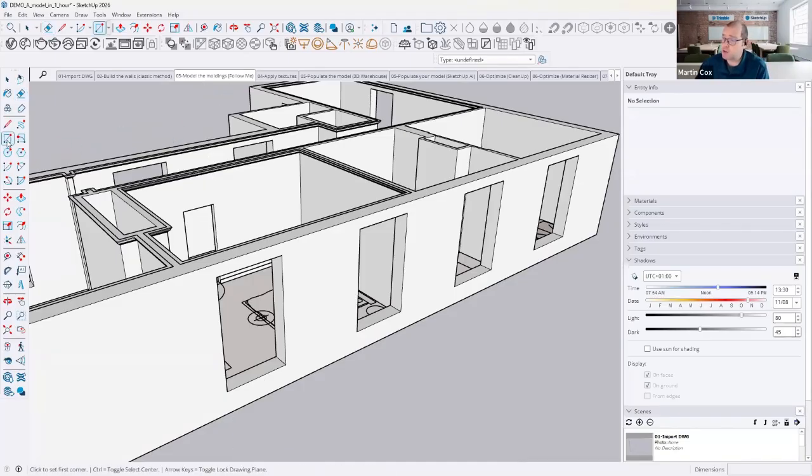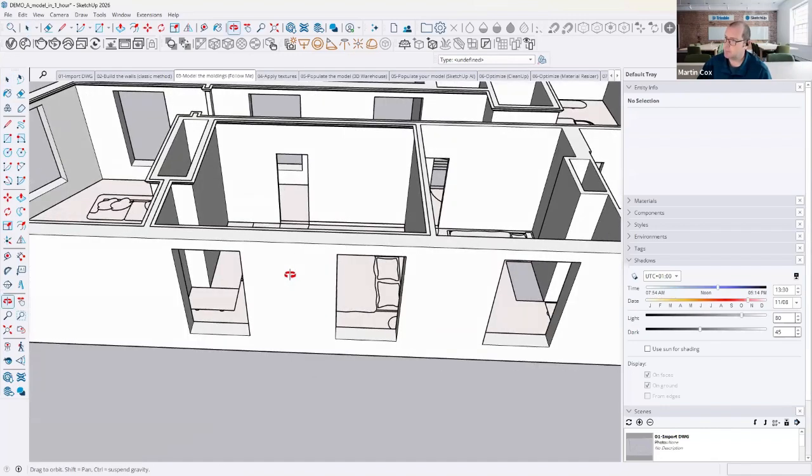The other option is when you draw a rectangle, if you look at the bottom right-hand side of my screen, it's giving me the dimensions of the rectangle, and I could actually just type in, if I want to show a rectangle that we can see here, 2 meters, 1 meter, that will draw a rectangle that size for me. So the accuracy that you can have in SketchUp, you can literally go down to 5 points in a millimeter. So the accuracy is quite a lot. Okay.